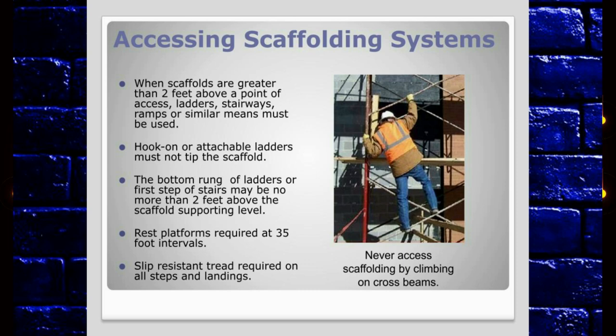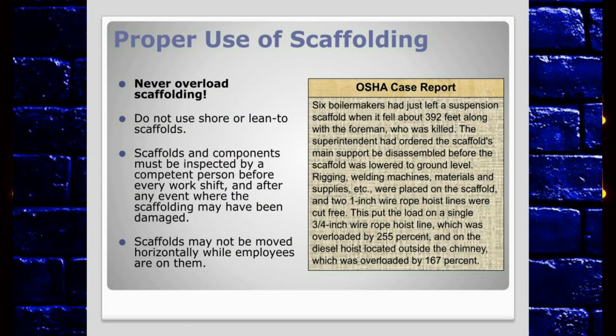Slip-resistant tread required on all steps and landing. Never access scaffolding by climbing on cross beams like this gentleman pictured here. Proper use of scaffolding. Never overload your scaffolding. Do not use shore or lean-to scaffolds. Scaffolds and components must be inspected by a competent person before every work shift and after any event where the scaffolding may have been damaged. Scaffolds may not be moved horizontally while employees are on them.